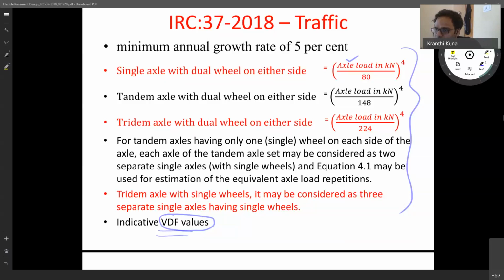This is a good question actually. Mr. Chakravarti has asked why we are considering 0.8 megapascal for cement treated base instead of 0.56 megapascal for all the other analysis. We use 0.56 for rutting on the top of the subgrade and fatigue at the bottom of the bituminous layer.